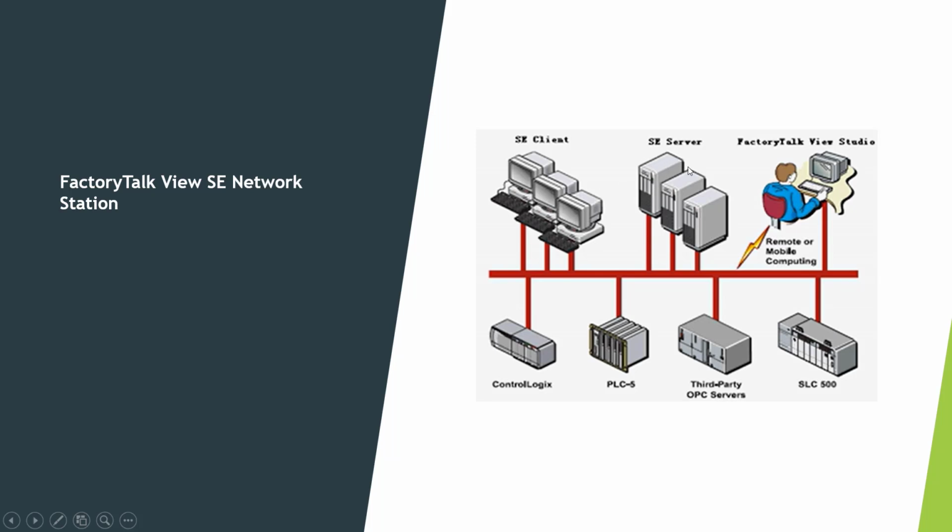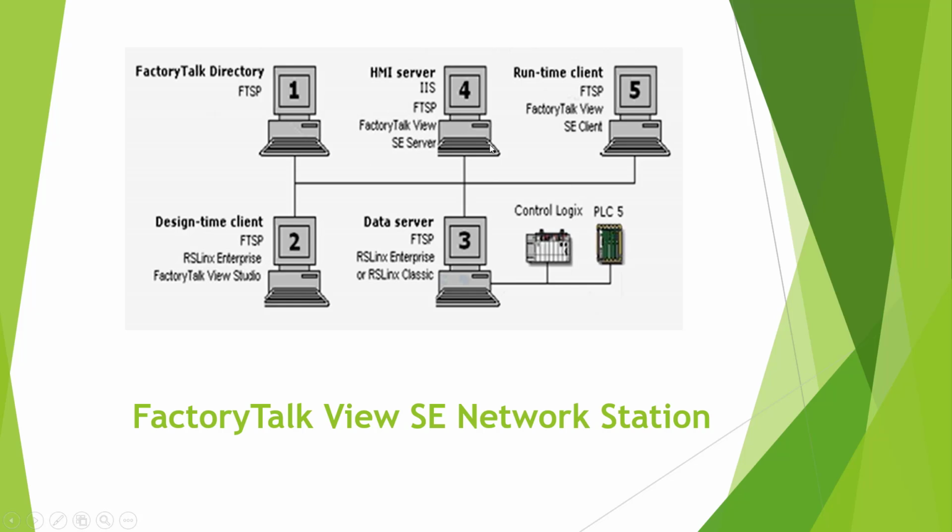There is the SE service. The SE service includes data service, FactoryTalk Directory service, and HMI service on different computers. Here is the FactoryTalk network station, how they communicate with each other and with the PLC control logic. The data server is here, and here is the HMI server. So that is called the FactoryTalk View SE network station.